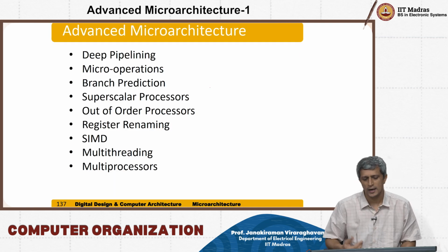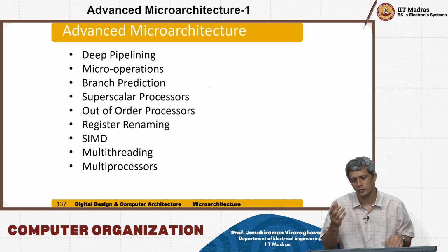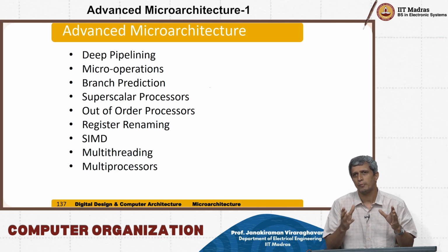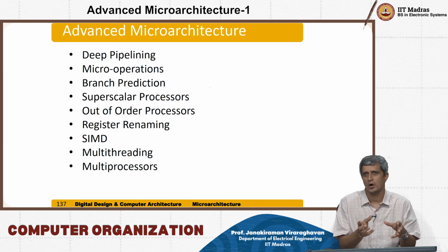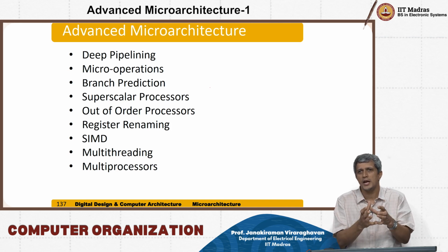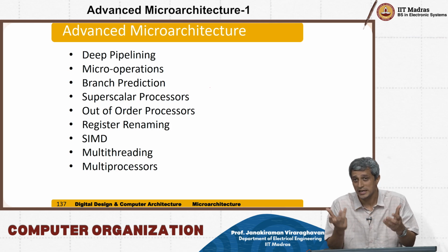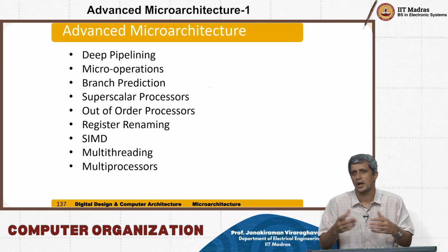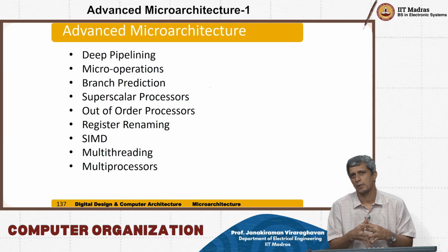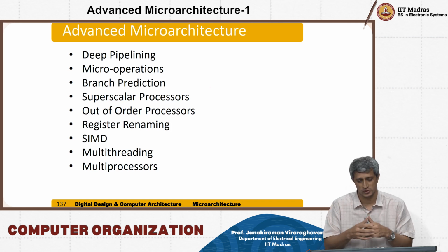So today, in microprocessors, there are a lot of other things which are done. We stopped with the discussion of a pipelined microprocessor. Basically, we wanted a very small clock period, but a throughput of one instruction per cycle. Ideally, if there is no stalling or branch prediction and all, that would be the case in a pipeline microprocessor, but that is not sufficient to meet the compute requirement of today's workloads, right?